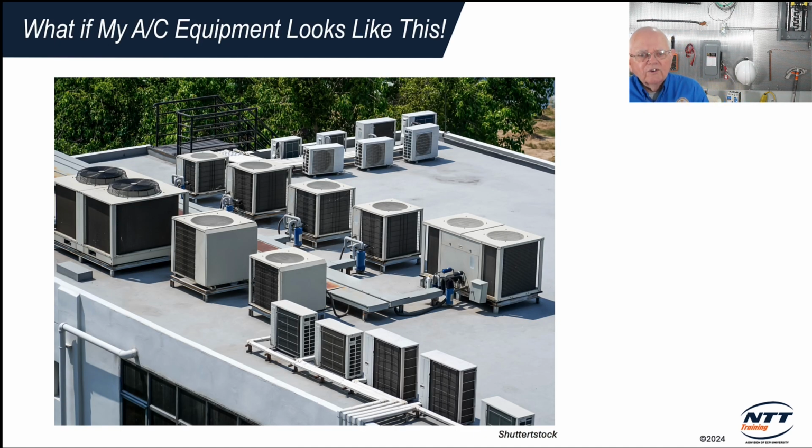Now, what if you don't have the typical installation? You walk up on a rooftop like this and you take a look and, oh man, I've got all kinds of units up there. They're all on the rooftops, right? So we've got rooftop units, but even these larger ones, if they're a rooftop unit, are most likely going to have the same setup as that condenser, except it's mounted up on the roof. Might have 2 fans in it or more. It'll have a larger hermetic compressor. It's still got the nameplate on there. Follow the rules on the nameplate.